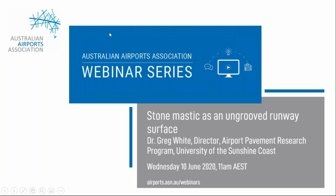Certainly there's the potential that the stone mastic surface will close up a little bit under lots and lots of traffic. So the stones might roll over and bed themselves down a little bit nicer, and that could potentially reduce some of that texture. But I think on the flip side, just the natural erosion of the surface over time would probably largely offset that.